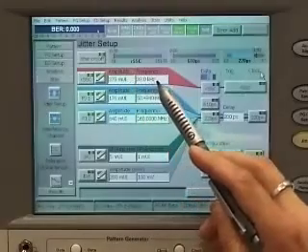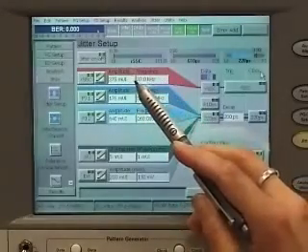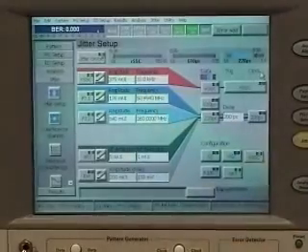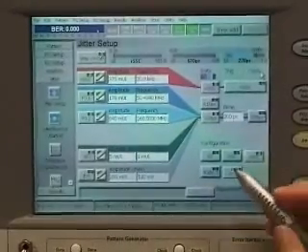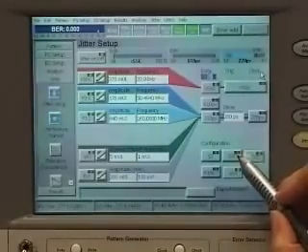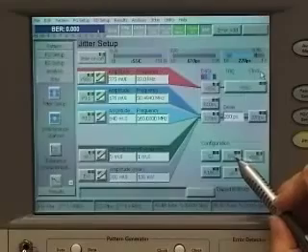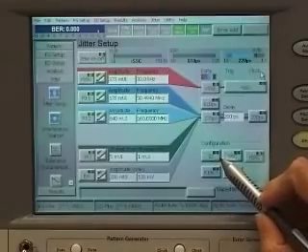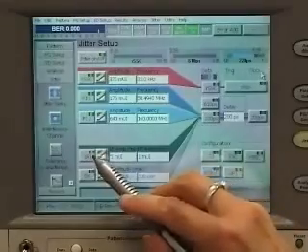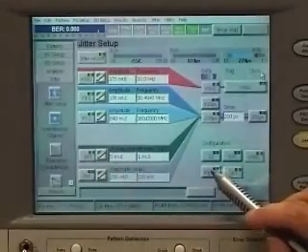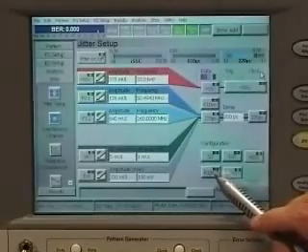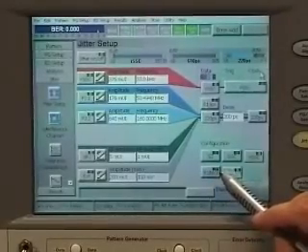Here you can also set the modulation frequency and the 75 picosecond modulation amplitude. If you don't need residual SSC, you can use this instead for spread spectrum clocking or for sinusoidal jitter. If you don't need spectrally distributed RJ, you can also set up a normal random wideband RJ and bounded uncorrelated jitter.